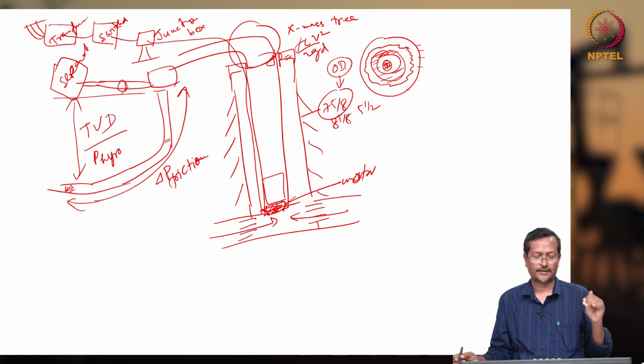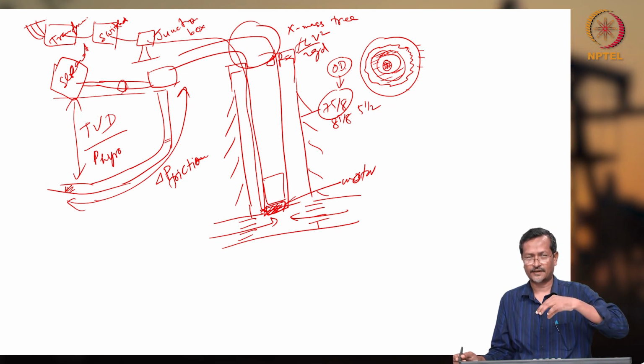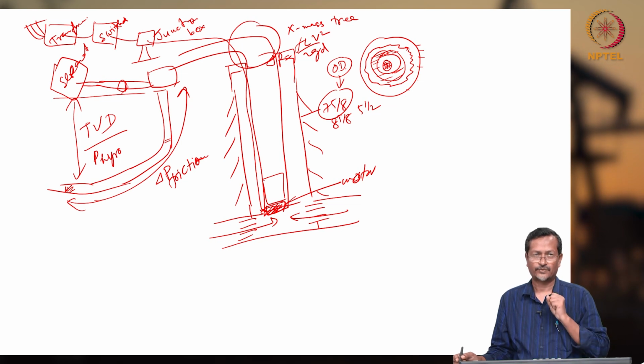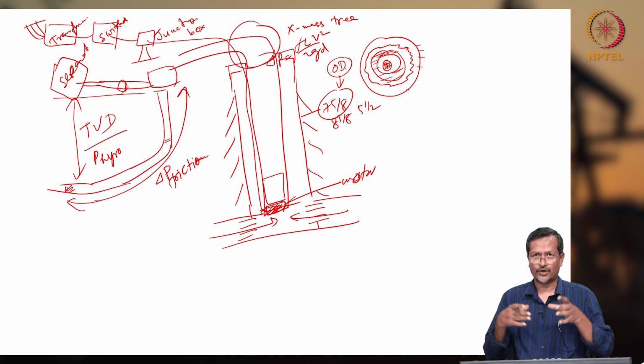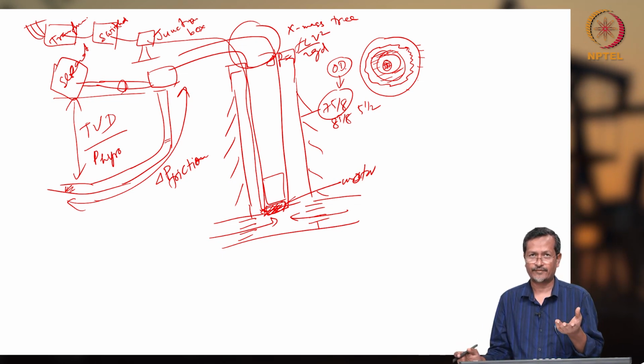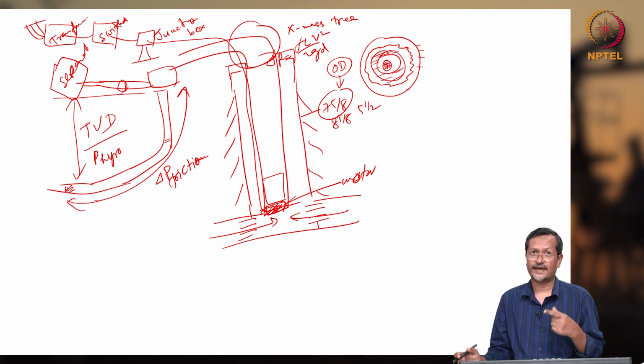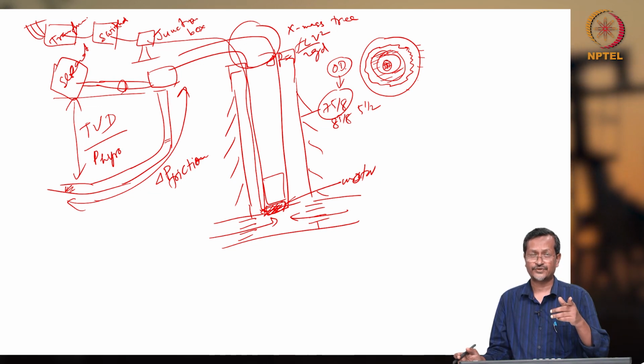Okay, so whenever you are installing any subsurface electrical submersible pump, what are the things you need to know? You need to know how much pressure you are generating, what your casing size will be, what your tubing size is, how much flow rate you are having, what fluid properties you need, whether sand is coming or not, whether gas is coming or not, the gas liquid ratio, and the sand properties. Then whether it is creating two-phase flow; the phase diagram also you should know.